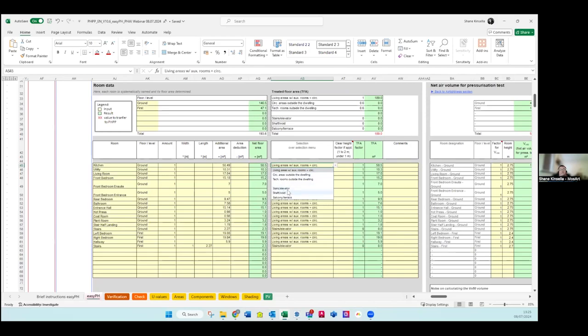Of course, elevators and lifts are rarities in single dwellings, but not unheard of. But you will obviously have stairs in most dwellings. Shafts and voids, you can decide yourselves whether to put those in. Those spaces go in as normal, and you can select their type. Then balcony or terrace: if you're measuring a balcony or terrace, you would typically classify that as 0, so you may just omit that from the calculation. It's a category I would rarely use in day to day modeling.